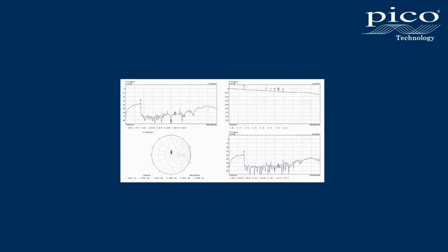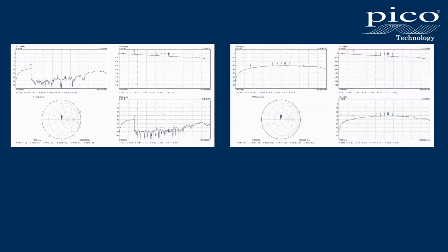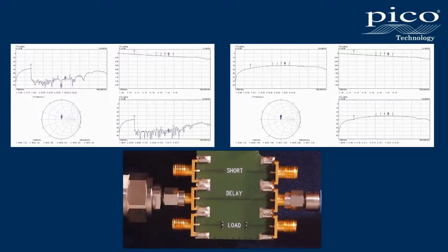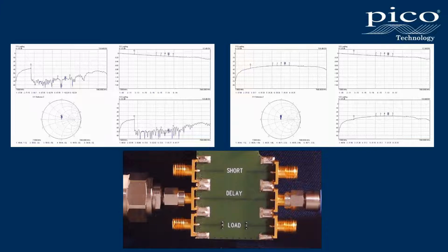The resulting discontinuities, here very large, we were able to correct to an extent, thus. But even here on the right, S22 not quite as well corrected as S11. In effect, we used a single correction based on port 1 to correct two ports using different TRM match resistors and two ends of a line that are slightly different via two feeds that are slightly different. All of the components have finite differences and can't really be corrected by one single correction.